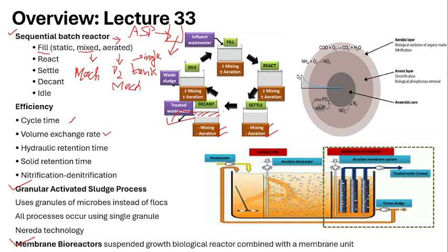So, how much volume is going to be filled and refilled again and again? How much is going to be taken out, how much is going to be filled, what is the volume exchange rate. Next is the hydraulic retention time. Again, what is the retention time for each wastewater. Next is the solid retention time. How much time the water is retained, how much time the solid sludge is retained. Both are very important to ensure the efficiency of the treatment process.